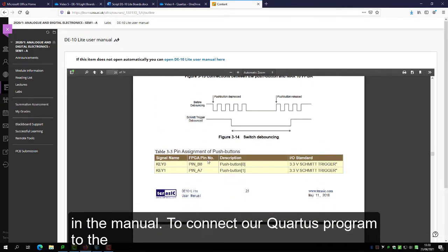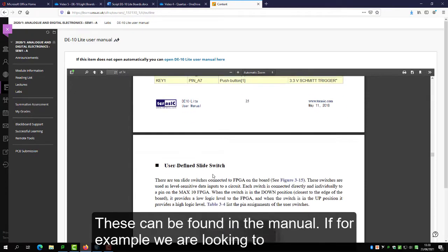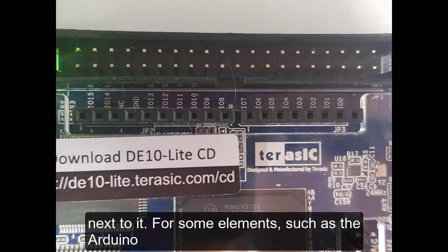To connect our Quartus program to the board, we need to know the pin names of each component. These can be found in the manual. If, for example, we are looking to turn on switch 8, we can go to the switches section in the manual and find the entry for SW8, which will have the corresponding pin name next to it.